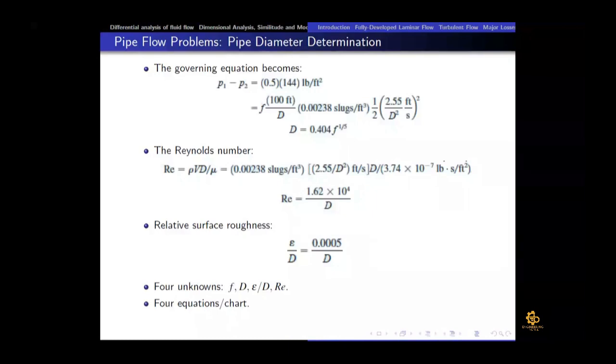Iterative solution means that we would assume a parameter and then do the calculation, and in the end we match the assumed value with the calculated value. If the values are equal, then we say that the solution is good enough. Otherwise, we repeat the iteration with the new calculated value of the parameter. In the pipe flow situation, we usually use the friction factor, proceed with the calculation, and in the end we again calculate the friction factor. So how can it be done?